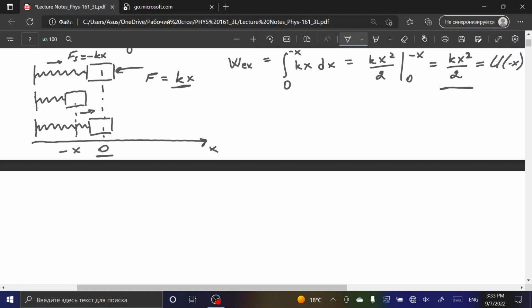Then what is the initial velocity? It is 0, because here it just stops. So good, we have the initial position and initial velocity. However, we need acceleration also. And in this case, the spring force is a function of position, meaning the force is not constant. If force is not constant, acceleration is also not constant. So you cannot apply the simple equation which we derived previously for motion along a straight line with constant acceleration, because the acceleration of this block will not be constant.